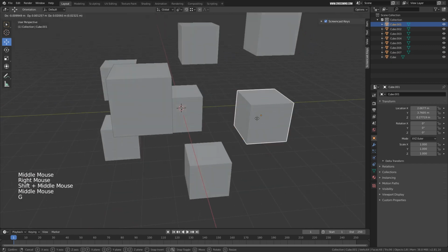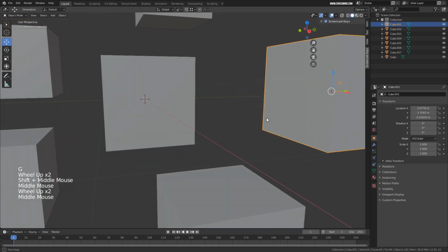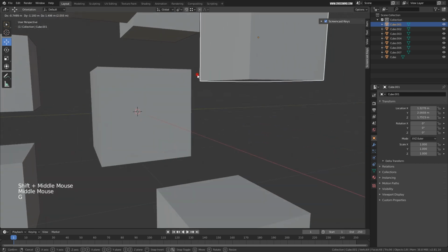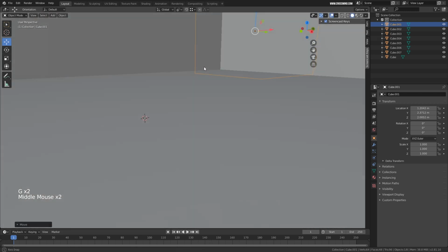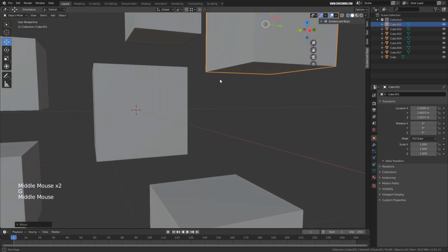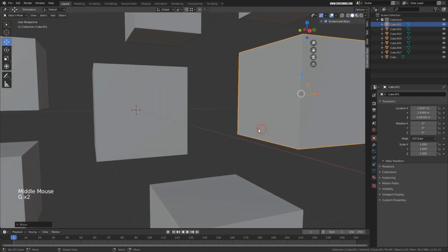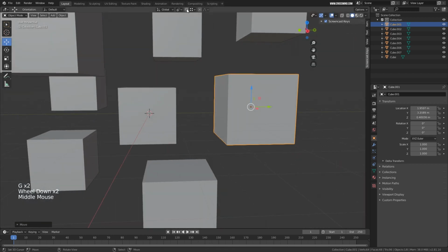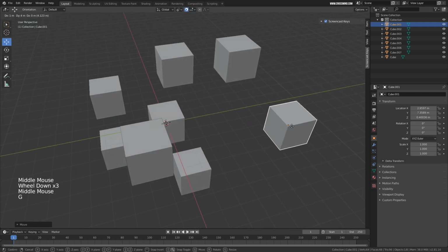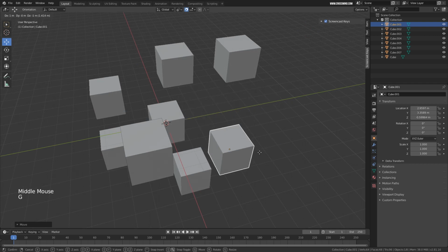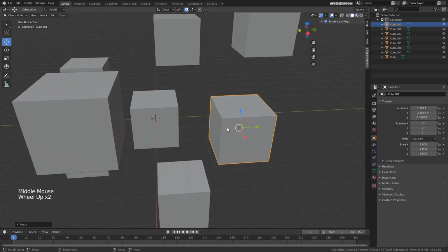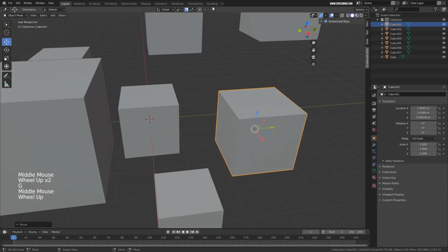So right now, if I want to move this point, this vertex over here, then it might take me several attempts to match it to that corner. And what I can do is use this option, the snapping. Now by default this is set to increment. What this does is, if you try to move your object, it will use the grid and incrementally move your object. Now if I change this one to vertex, see what happens.